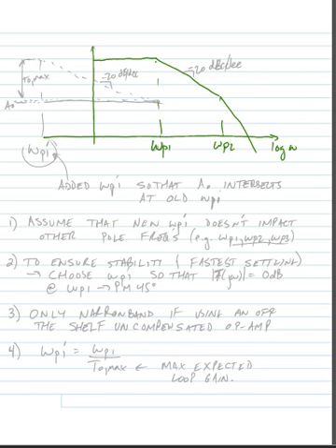What we're going to do is add another pole that has a much lower frequency than our original omega P1. So let's say that we decide we're going to lower the pole so that we get a roll-off that starts way back here in frequency. Okay, so this is our new pole here. We'll call it omega P1 prime. And of course this is now our 20 dB per decade roll-off. This was our original 20 dB per decade roll-off.